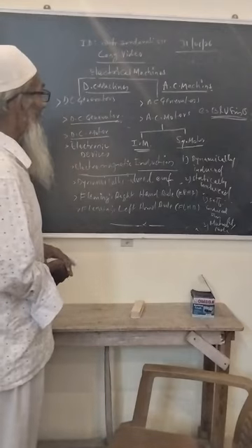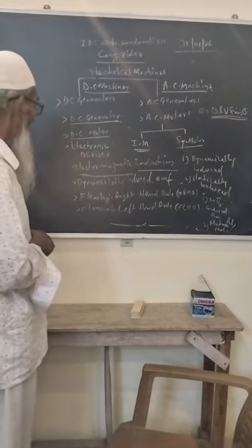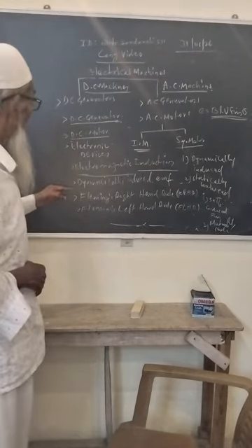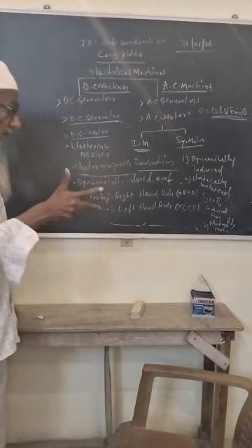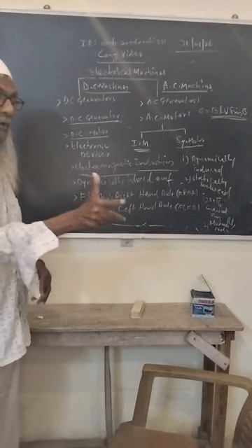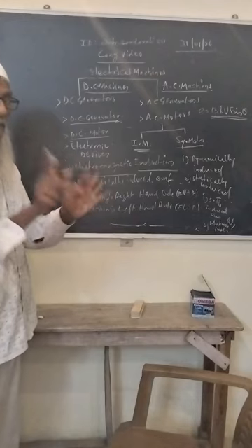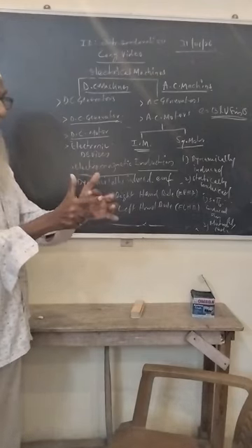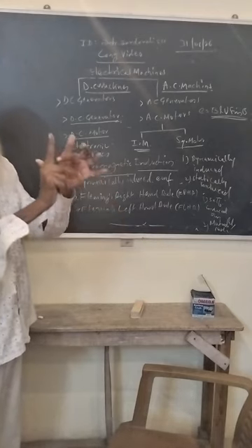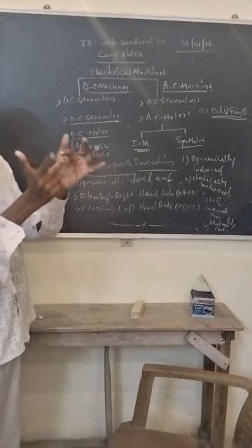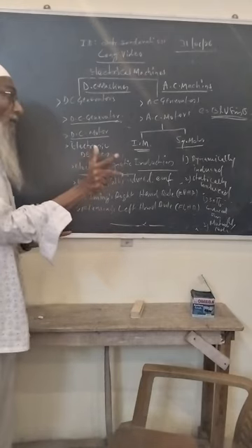Now, dynamically induced EMF, wherever it is induced in DC machines, is given by Fleming's right hand rule. In Fleming's right hand rule, hold the thumb, forefinger and middle finger of the right hand mutually perpendicular to each other. The meaning is that the thumb is perpendicular to the forefinger, which is perpendicular to the middle finger, and the middle finger is perpendicular to the thumb.